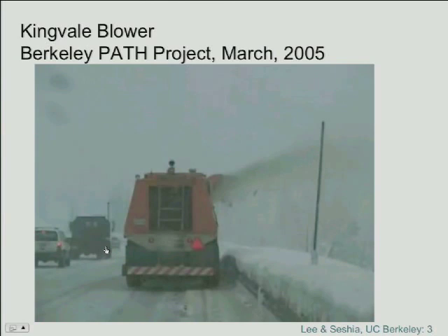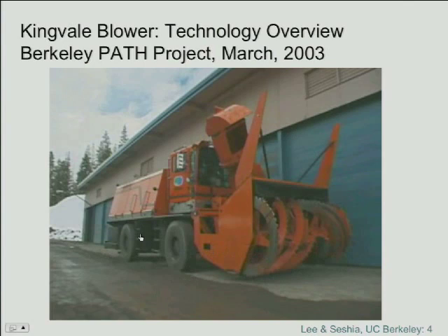Okay, it's a sensor array bar, so there's a row of sensors. One of the sensors will pick up the magnet more strongly than the others. If it's a sensor to the left that's picking it up, then the snowblower corrects by driving to the right. If it's a sensor to the right, then the snowblower corrects by driving to the left. Pretty much exactly the same kind of feedback system as we saw for the helicopter control system.